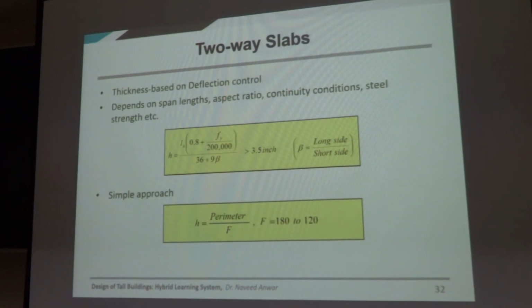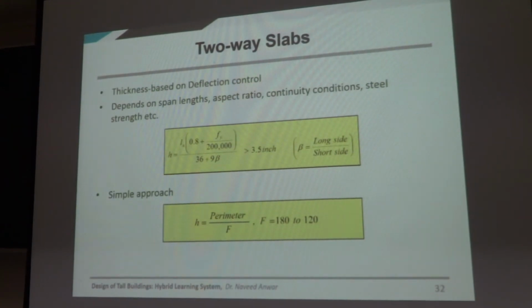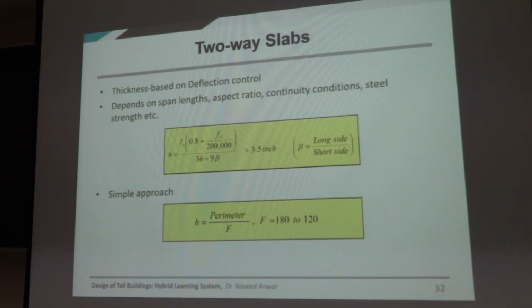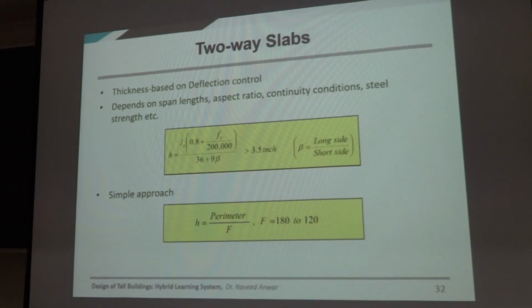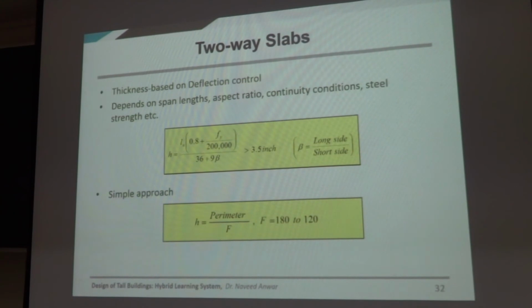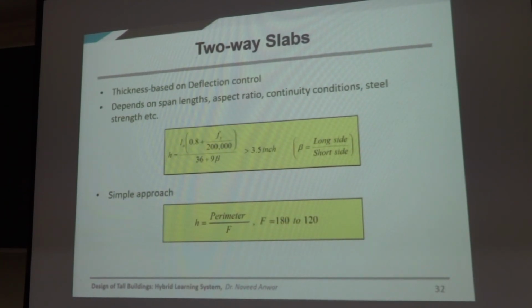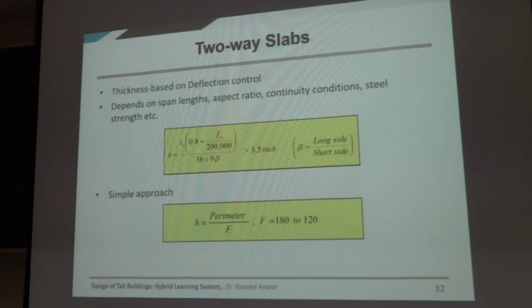And when you multiply the amount of reinforcement by the modular ratio, which is 10, the effect on the moment of inertia is quite large, especially of a cracked slab, where the concrete is already gone. So most of the stiffness of a cracked slab comes from the steel stiffness. And steel stiffness depends on the elastic modulus multiplied by the amount of steel. And the amount of steel will be higher for low strength steel than for high strength steel. That's why this whole thing is there.